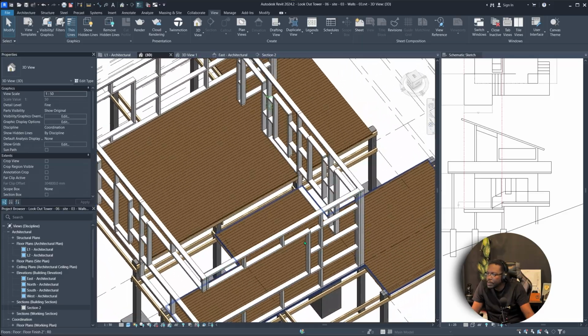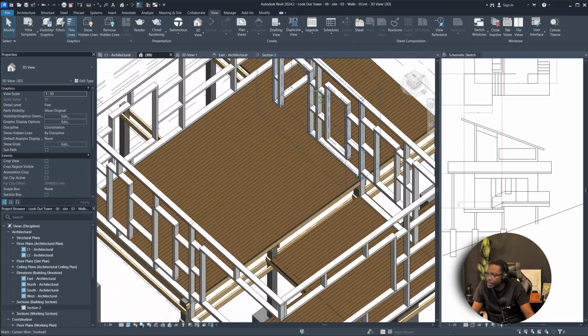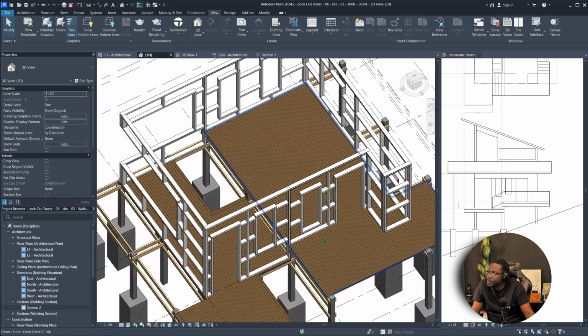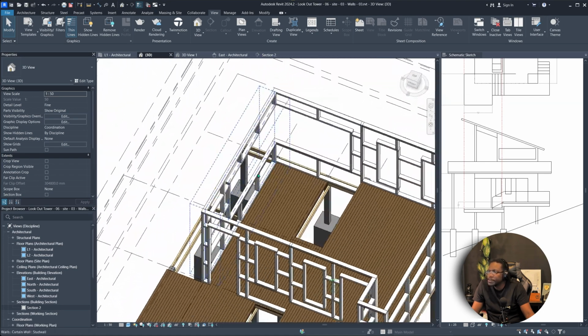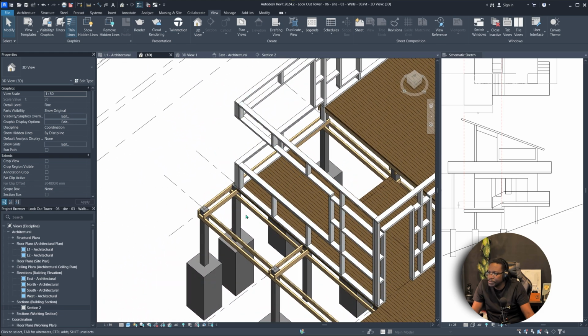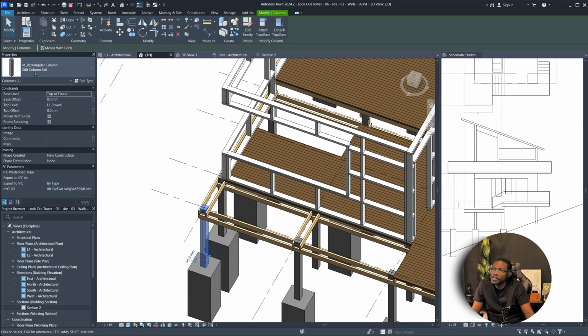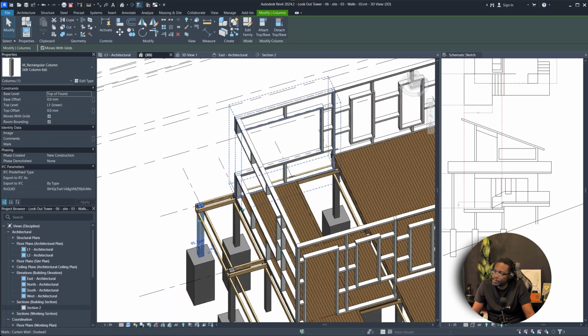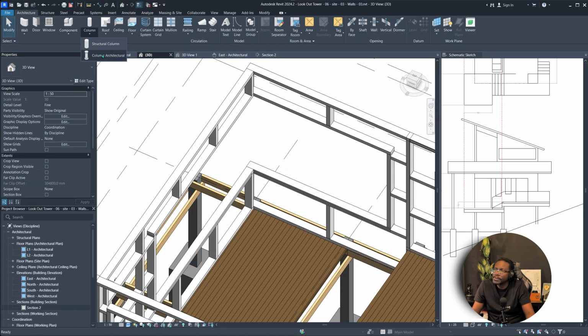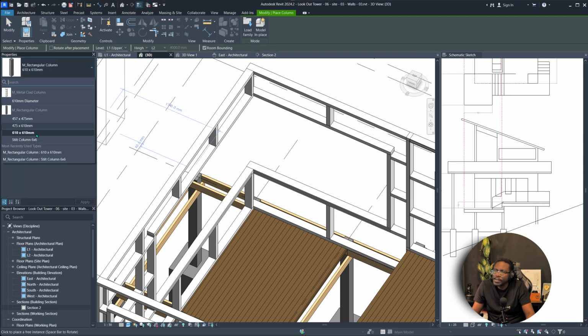Now we are going to actually put a rail in here that goes down, so we'll do that at a later time. We need to put the column here that goes all the way up for the structural support. So we can use this stilt column that we used before. So we're going to go to column, and we're going to go to architectural column, and there we go.